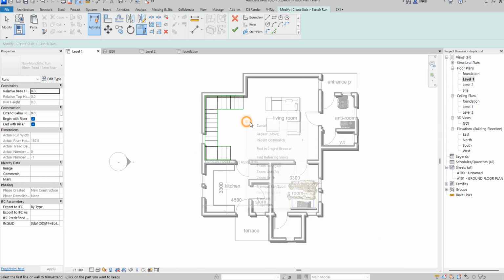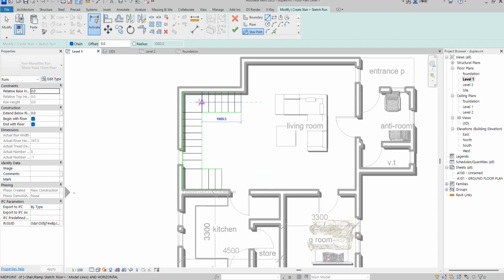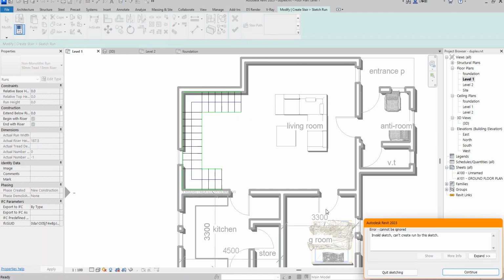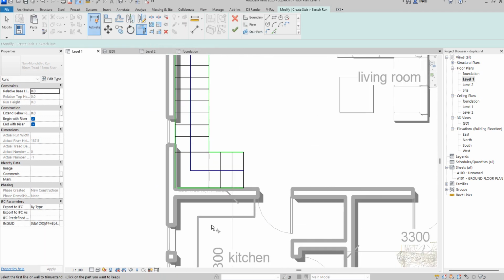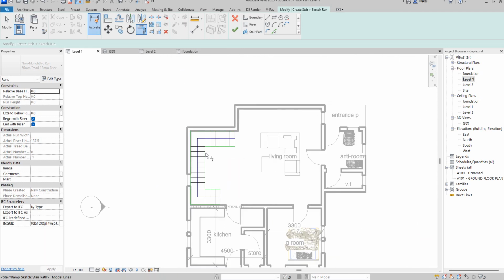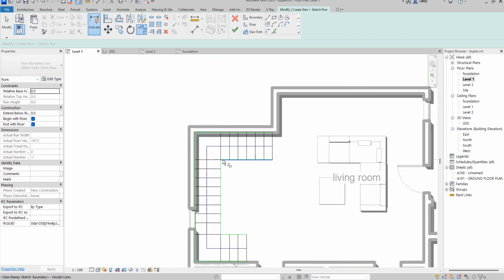So that's it done. Now as you're done, if you click finish here, it's not going to flow. You need to put parts. So I'm starting my journey right from down here, coming here, join there, and then edit up at the level here. So I'll click OK. So what is it saying? Invalid sketch created run by what? So what is my issue? The invalid sketch is creating runs by this sketch. So continue. The problem is that you need to find where there's a loop or disconnect. So that is where the disconnect is.